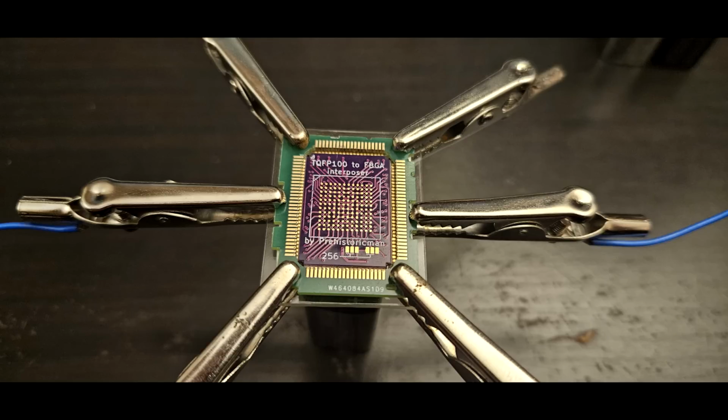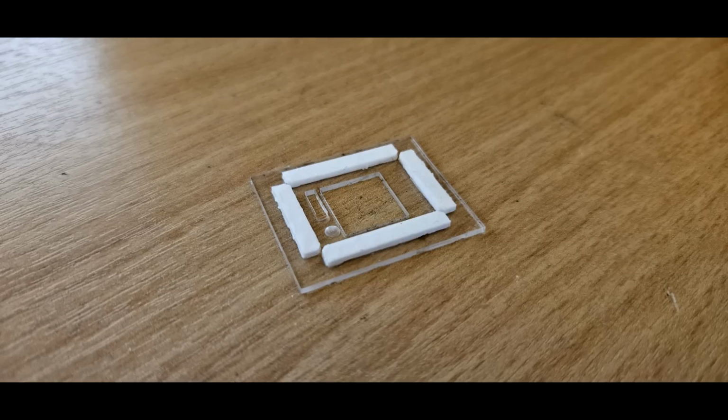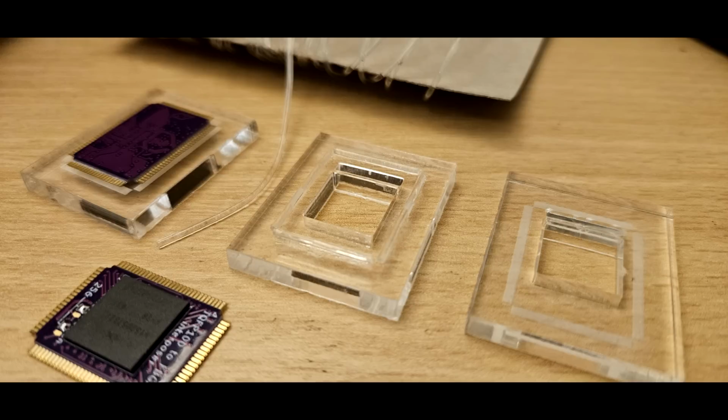Finally, I realized that this solution with the silicone is not providing a good contact patch. Due to the width of the silicone here, a lot of force is being wasted. I'm applying pressure to the top, but that is not providing pressure to the electrical contacts. So what I really needed was a very thin line, about 1 millimeter thin, to provide force onto the flex and then onto the electrical contact. So that's when I came up with the winning solution.